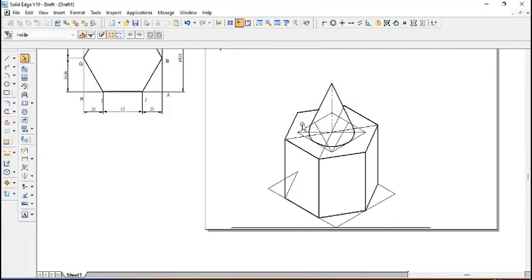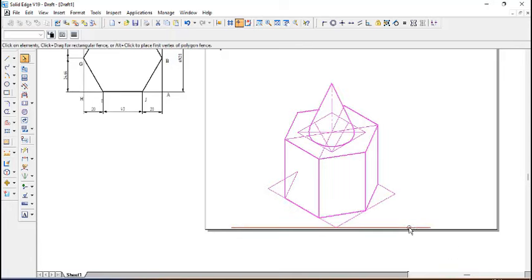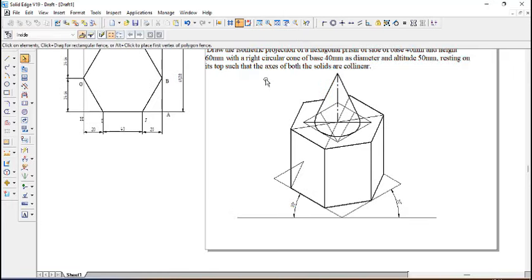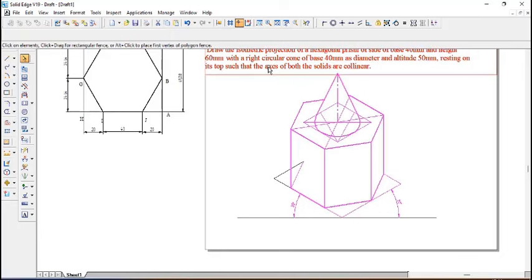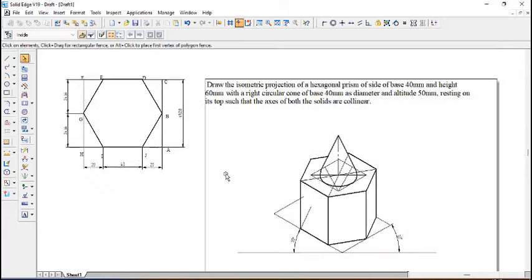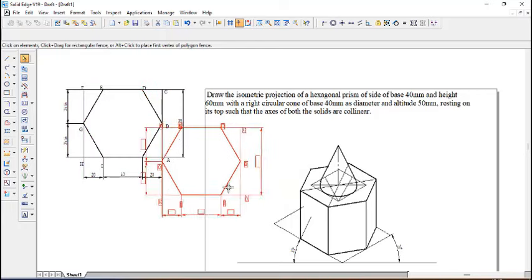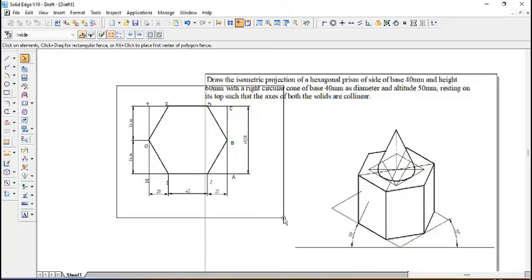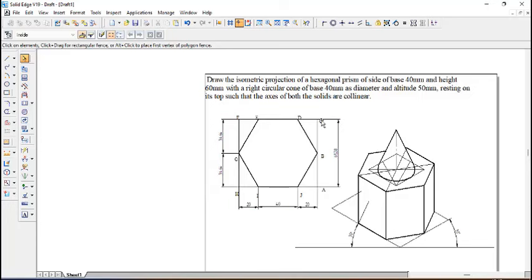So once this one is done, now our duty is to just move this one up and show the 30-degree angle. 1 and 2, and select everything. And go to the scale command, copy off, it's a point 8164, enter. Place it on the line. That's it. And keep this hexagon in the printing area. That gives 25 marks to EP.